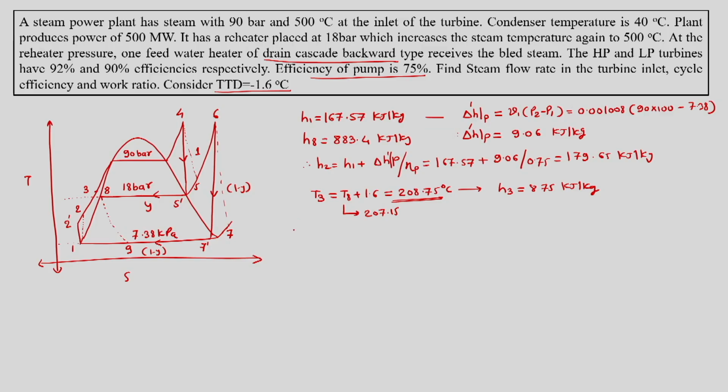We can as well find out this enthalpy from liquid tables, and then these enthalpies would almost be similar. So for that fact we have now H4, which is this, and we know it is 500 degrees Celsius. So for that, H4 is equal to 3386.1. We will keep also noted S4, which is 6.6576. So we know that S5 dash is equal to S4.